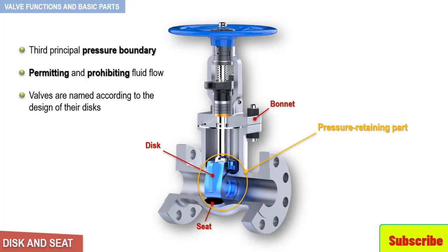To improve the wear resistance of the seal rings, the surface is often hard-faced by welding and then machining the contact surface of the seal ring. A fine surface finish of the seating area is necessary for good sealing when the valve is closed. Now, keep in mind, seal rings are not usually considered pressure boundary parts because the body of the valve has sufficient wall thickness to withstand design pressure without relying upon the thickness of the seal rings.